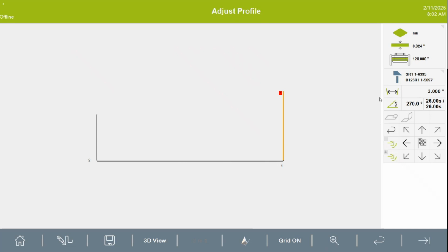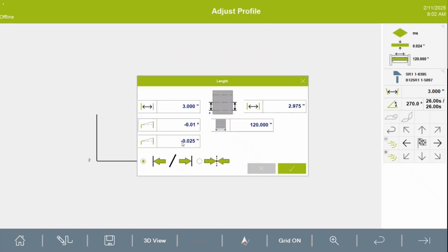Still only have a disparity of 0.025, right? And that's a little bit lenient. If you're within 4 thousandths, 0.1 millimeter plus or minus of that number, you're not going to get a triggered alarm on that delta. If you stay at 4 thousandths and under, then you're fine if you don't type in exactly the same number. But once you get outside of 4 thousandths, it's going to give you an alarm, because the tolerance is 0.1 millimeter between left and right from what the machine has calculated.